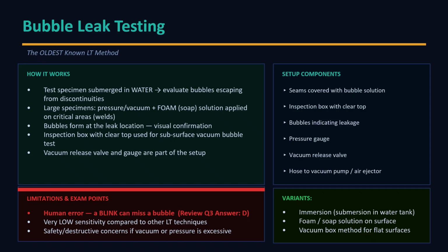Now let's discuss the biggest limitation. The detector is the human eye, and human eyes are not perfect. Poor lighting, fatigue, distractions, blinking, all can result in missed indications. This is why bubble testing has lower sensitivity compared to advanced leak testing methods.